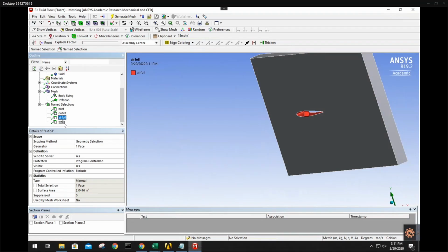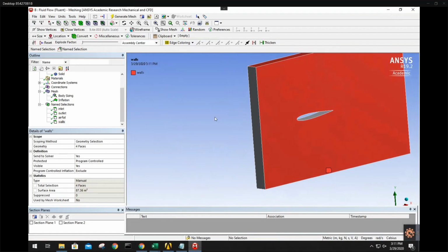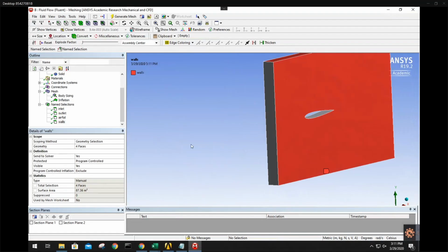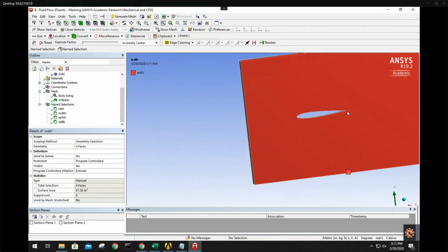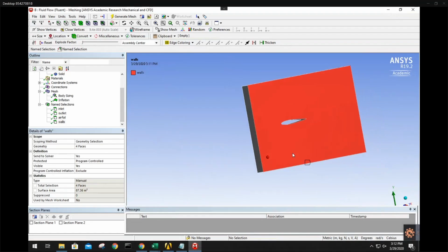outlet, airfoil walls. Dang, I should have chosen a dimension that looks more rectangular, this is a very slim rectangle. And actually, I'm only gonna do like 4 degrees angle of attack. I only made these far away because I was afraid that if I try some angle of attack, it might hit the wall or something like that. And if I was to set these as velocity inlets and I had it going up this way, that would give some wrong values. But I think this works.